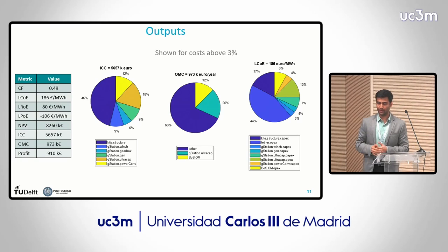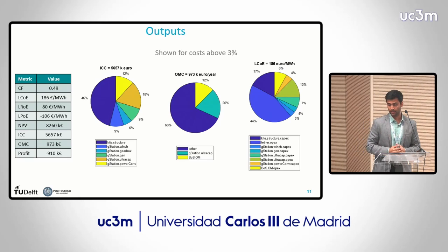So the central pie chart, where the tether replacement is actually 70%. So the frequency of tether replacement, what we find here, is almost more than once a year. And the driving factors for the tether replacements are really the bending under tension. And it really scales quite fast with the number of bends that you have per cycle. So if you have one drum, one sheave, if you have two sheaves, it really scales quite fast with the bends that you have with a loaded tether.